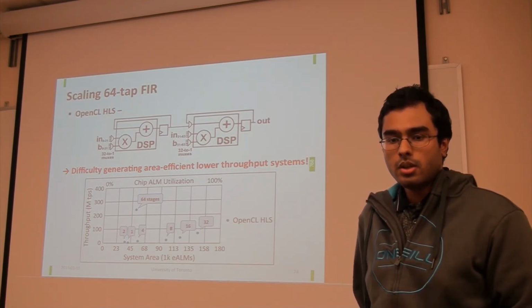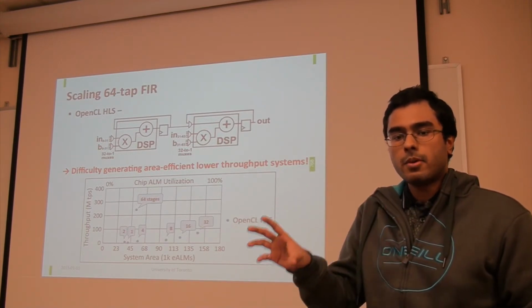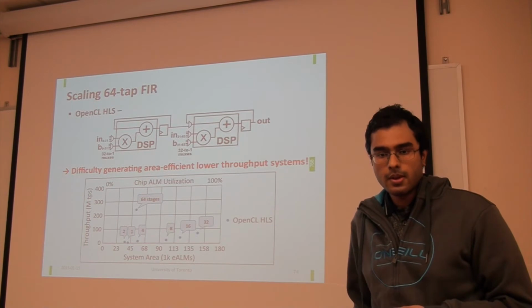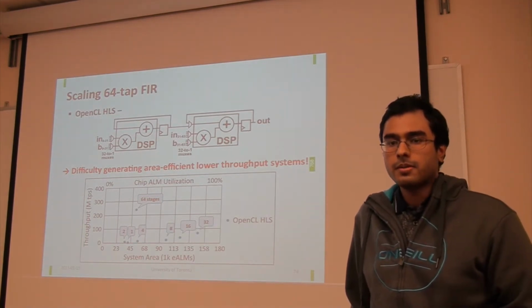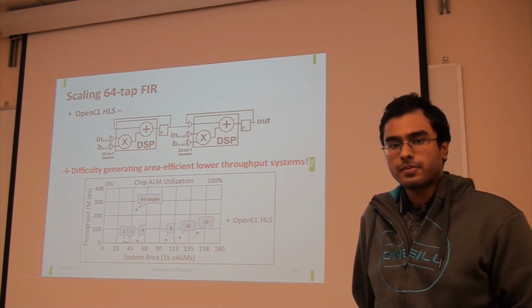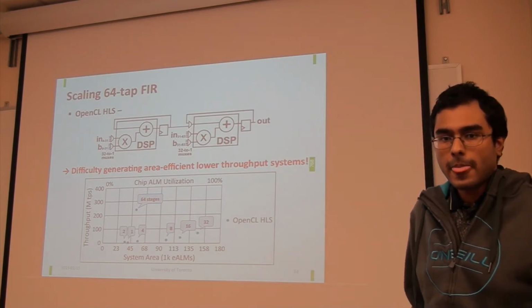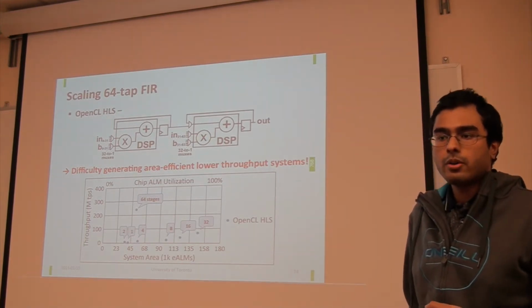Okay. So the numbers on the graph, 1, 2, 4, 8, 16, those are the number of compute units. No, those are not the number of taps. Does that make sense? Sort of. Okay. So with 64 stages, you don't need any muxes. Otherwise, you do need muxes because you're doing a 64 tap computation on fewer compute resources. So that was the main point of this graph.